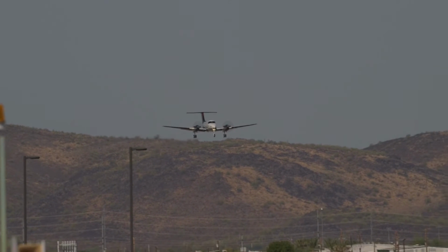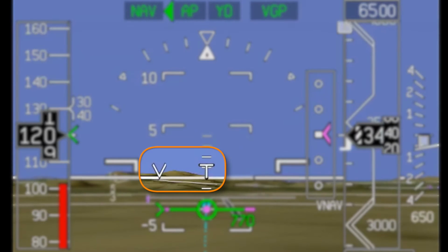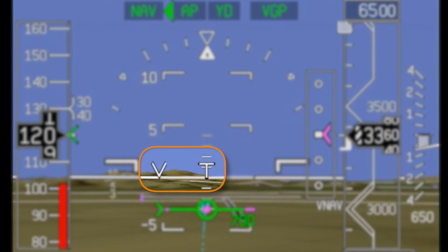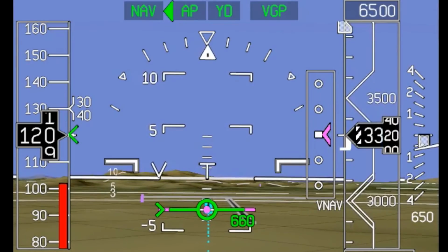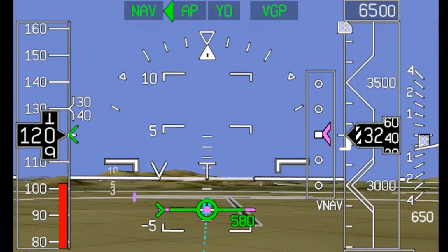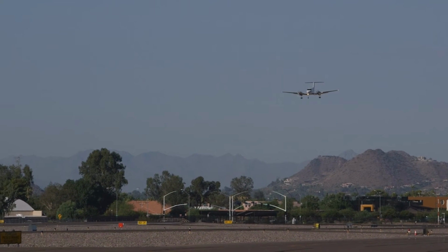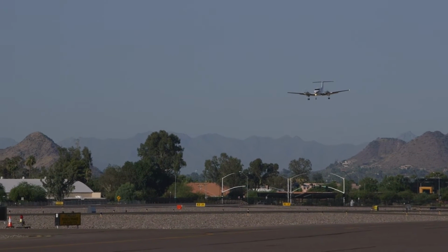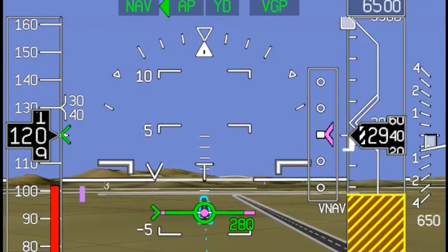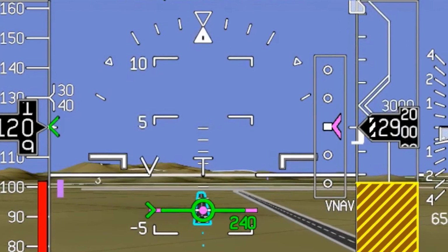During an approach, as the aircraft descends below 800 feet AGL, the size of the track and heading reference symbols gradually become larger. This continues until they reach their maximum size, which occurs when the aircraft reaches 600 feet AGL. This helps the pilot to quickly visualize the aircraft drift angle. It also helps the pilot estimate where on the windscreen to look for the runway during low visibility situations.